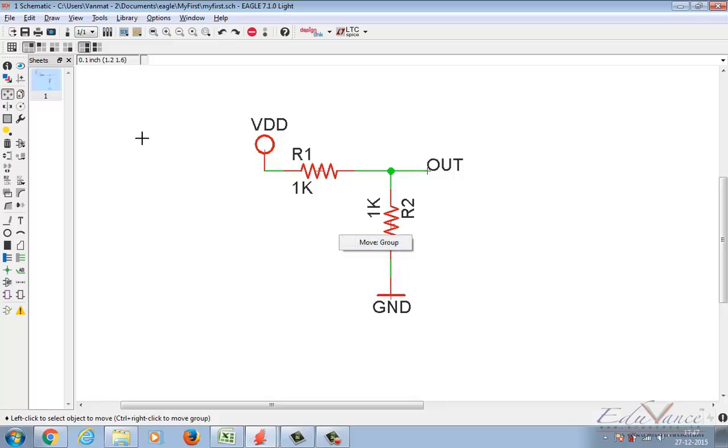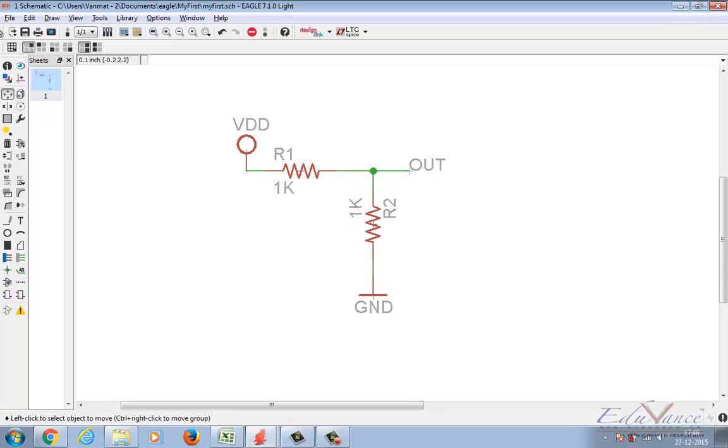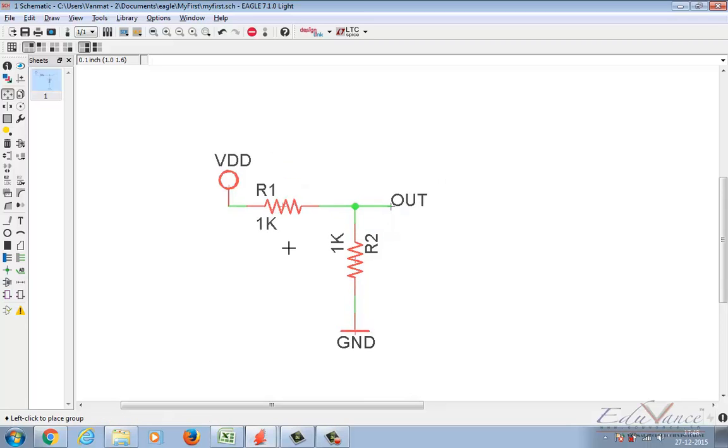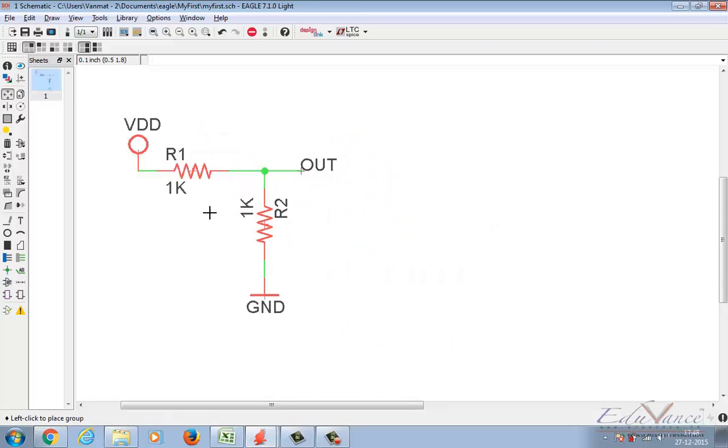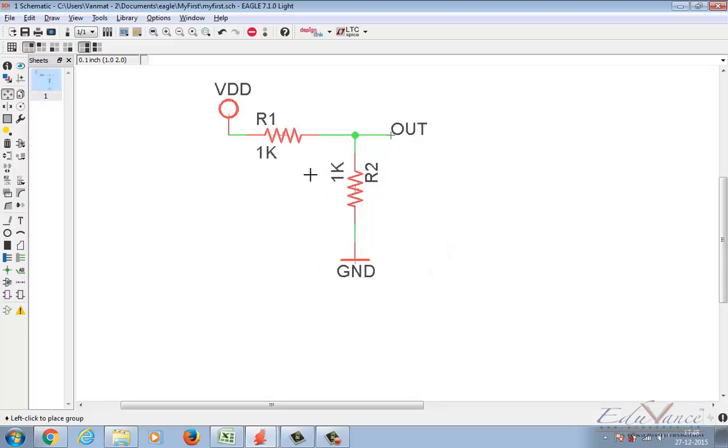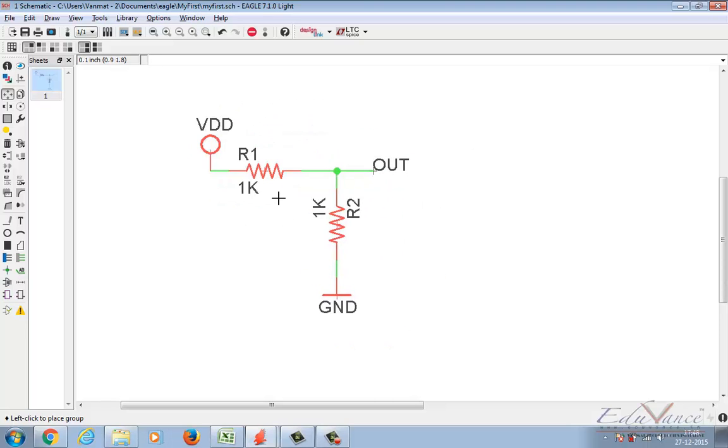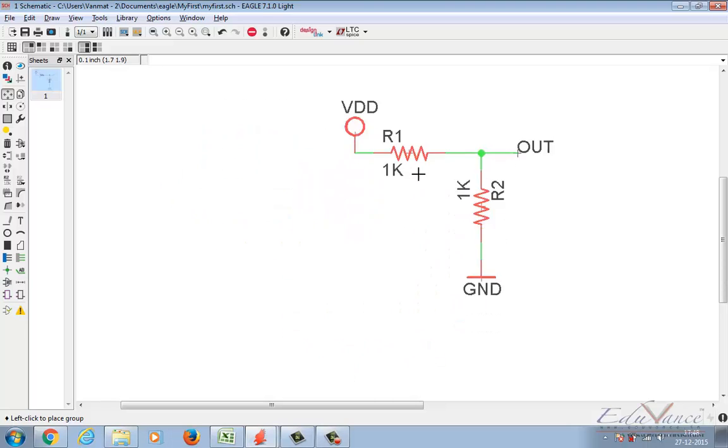Now a shortcut to this right click method, wherein you first have to select your area, select the tool, then right click and then move. Instead of these 3-4 mouse clicks, you can simply first select your area, then select the action that you want to perform, then press your control key and drag it along with your right click press. Control plus right click will mimic your action.